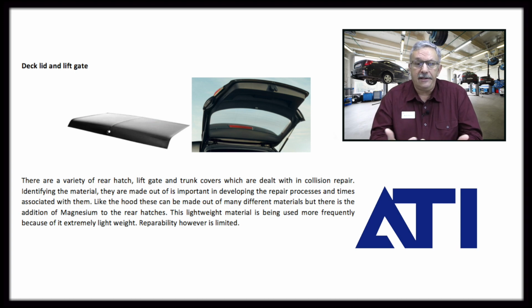We go into all data, let's say, we research the information for that part that we're going to fix, and I kind of use this as a rule of thumb that works real well. Anytime I'm going to heat a panel, for whatever reason, whether it's welding, cutting, whatever the case might be, I want to pull the data for that part specifically so I know what the repair parameters are. That will be the thing I want to do as a repair planner is I want to make sure that I'm providing the repair information that's required for that part to the technician.